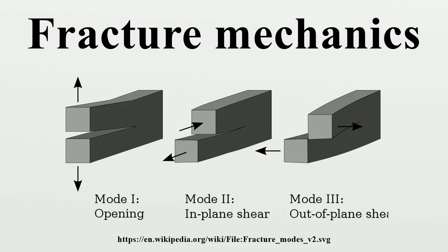Elastic plastic fracture mechanics: most engineering materials show some non-linear elastic and inelastic behavior under operating conditions that involve large loads. In such materials, the assumptions of linear elastic fracture mechanics may not hold, that is, the plastic zone at a crack tip may have a size of the same order of magnitude as the crack size.